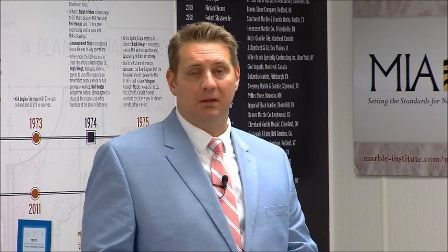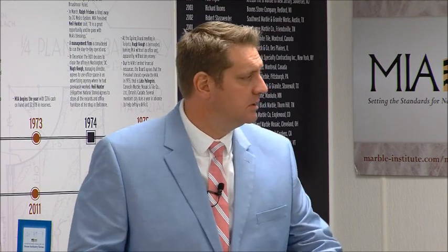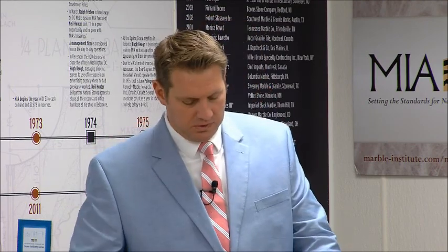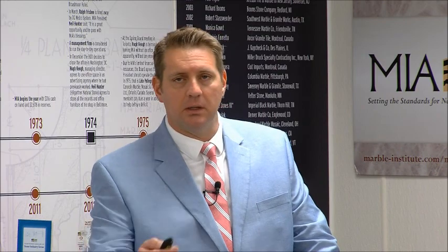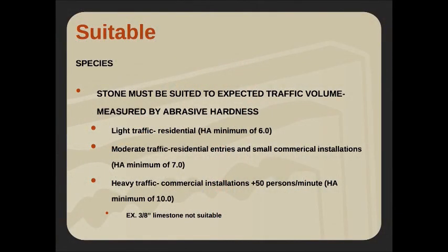Often historical, anecdotal information is the best when it comes to this sort of thing. I'm going to use a material that I know has been successfully used in a like environment. Let's talk a little bit about traffic volume for using it on the ground or in a flooring application. It's important that we understand that there is an abrasive hardness required.